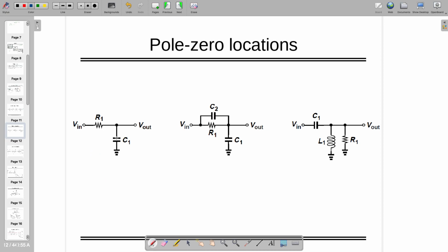Okay. Even here you can see that its capacitor is DC blocking. At low frequency, this will be blocked. This is what maybe Rohit was trying to do. So if you are having a multimeter whose input impedance is infinity, so if this is a very high value, let's assume infinity, then you are going to see V out equal to V in in that case only, right?